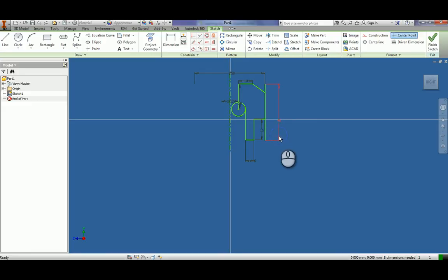You may have to go back and actually delete some of your dimensions. Otherwise, you may have a problem where they'll actually prevent you from trimming back the excess. For example, I'm going to have to delete this constraint too. And there's your shape, or at least your basic shape. So once this is done, you'll notice how all the dimensions are right and everything's good.